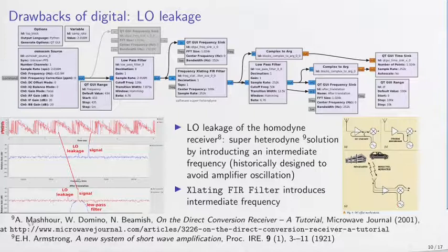So all these causes of a local oscillator not being perfectly isolated by the mixer and the amplifier and returning in the mixer will create this DC component, which by definition is centered on 0 Hertz. Now if we analyze the phase of this signal that we want to look at, because this local oscillator leakage is at a frequency offset, then we see in red here the phase information of this signal that is significantly noisy because of this spectral component here.